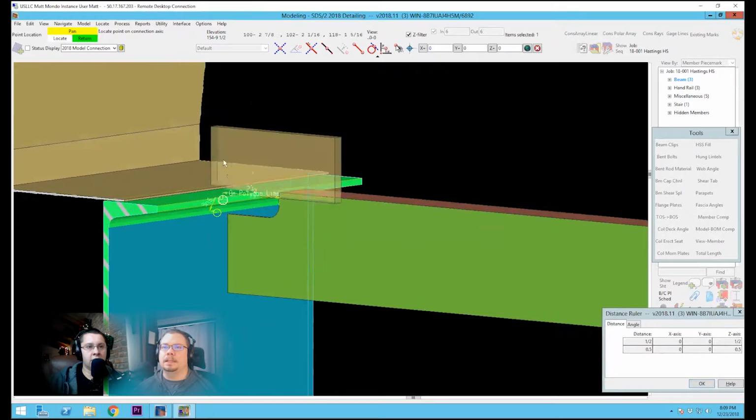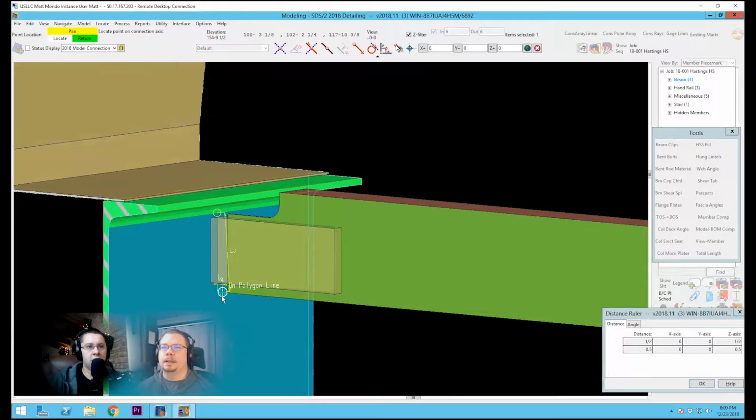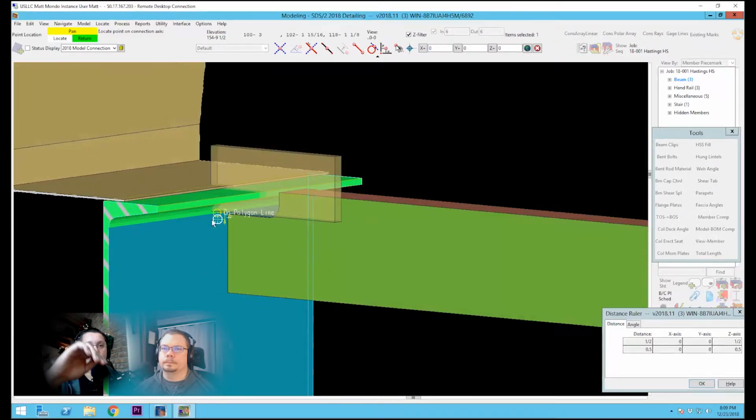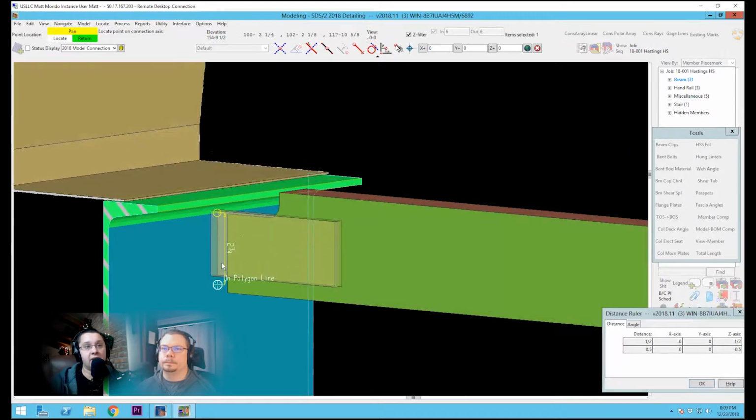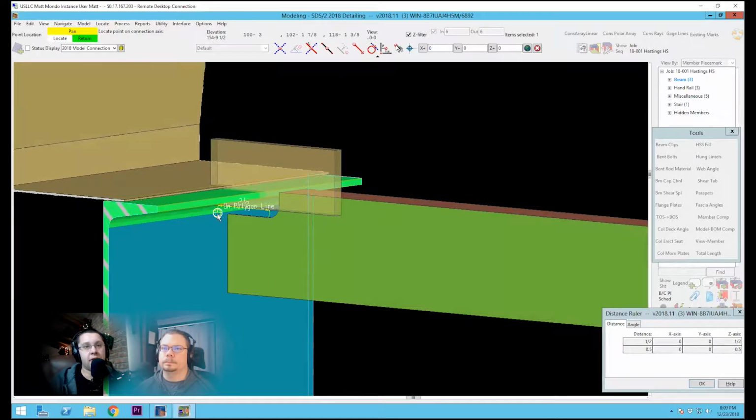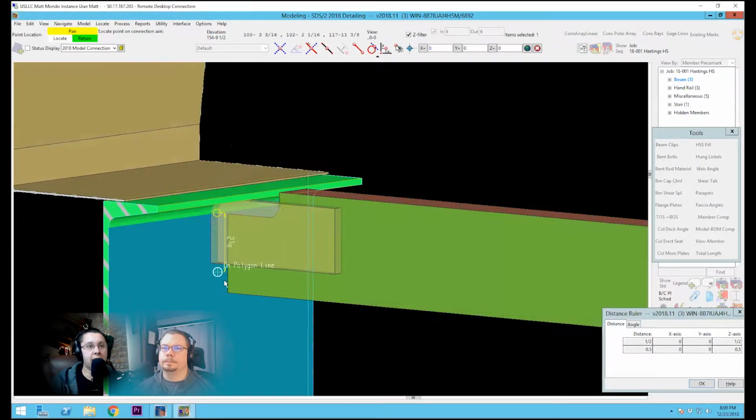Now, this is sort of an imprecise measurement. Just kind of eyeball it and get it about where you want it. Now, you can't really go wrong. I can't drag this thing off that plane, but yeah, you're just looking to get that vertical attachment. As you can see, too, it seems to reference, and we're not certain about this, we don't know the code, but it seems to reference the top of that surface. So in this case, it's getting to the top of the web before it starts to get to the fillet, and that's the reference point. So it's not really a useful dimension. You can't just type something in there. You got to kind of play it by ear and figure out what you need there.